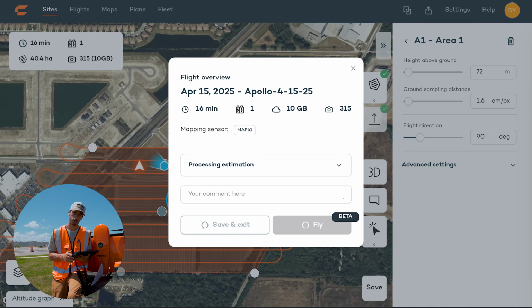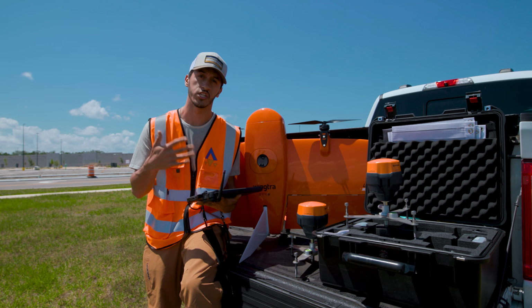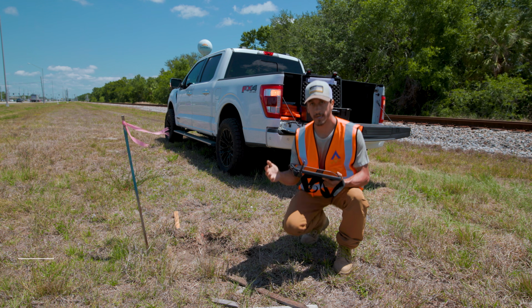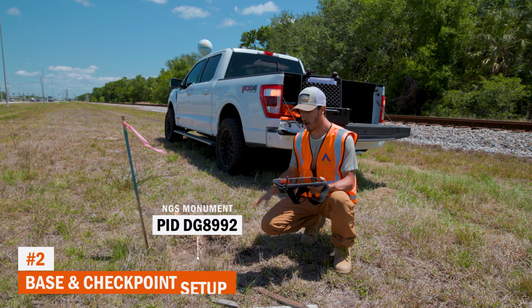Because now what we need to do is go to where we're gonna set up the first base station. We're gonna set it on an NGS monument. There's one about 1.5 miles away from here. So let me go meet you over there and show you how to get this next process done. Now that we made it to the actual NGS monument, we're gonna be setting up one of the base stations on this point right here.